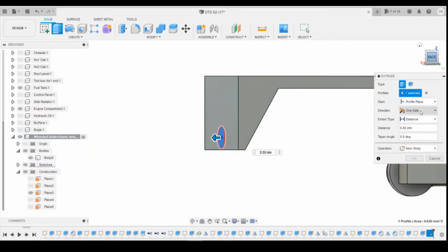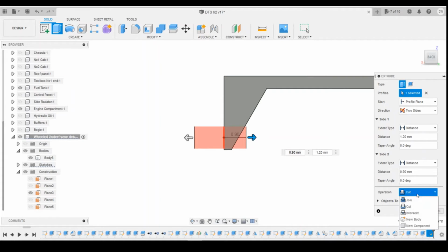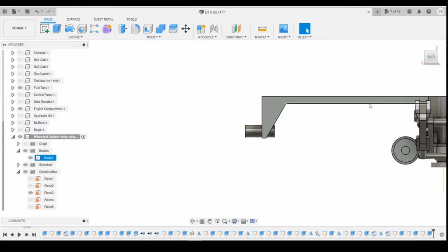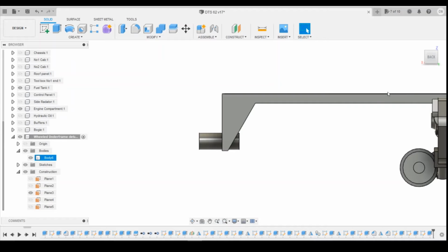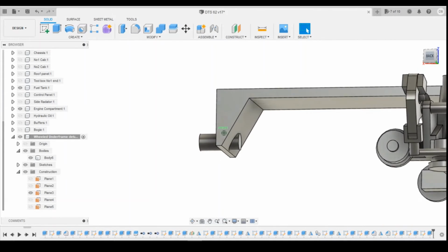We're going to turn that sideways and do 2 sides. When it sticks out, I'm going to come maybe 1.2 millimeters out that way. I'm just going to come enough through so it's going to come past the triangle section. So it's going to come 0.94. It's going to tell it to join. Click on OK. Good. Right.